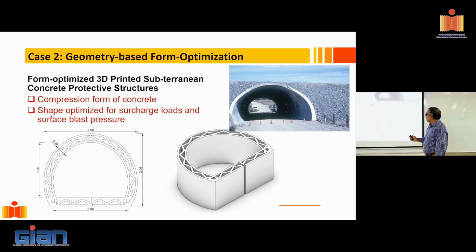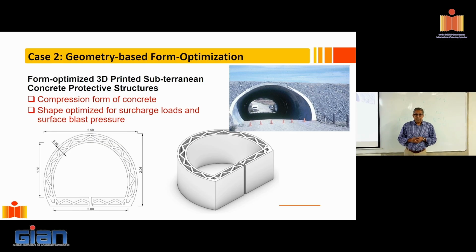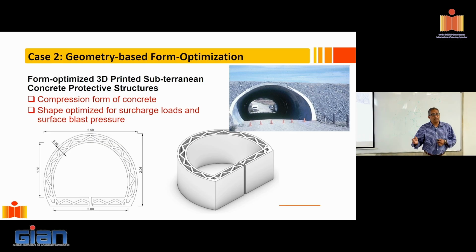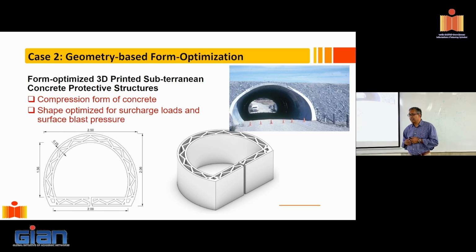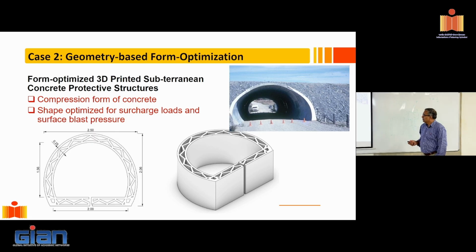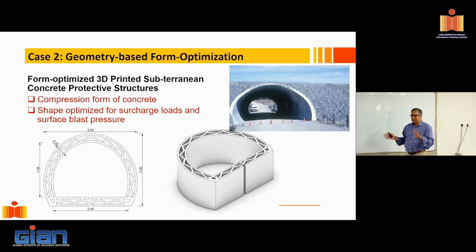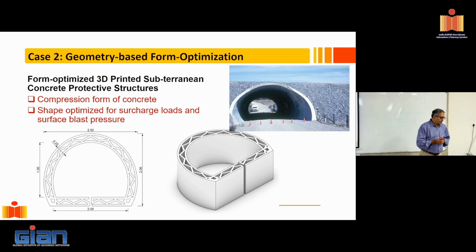So I can now start talking about underpasses. I can start, we are looking at airport hangars. For defense applications, now we are looking at protective bunkers for our soldiers. Of course, then we'll have to get into the concept of UHPC, which is a concrete which is much, much stronger than our regular concrete, much tougher, or has a much higher energy absorption. So with that, then we could start printing the structural shapes that are very, very resilient, taking advantage of geometry.